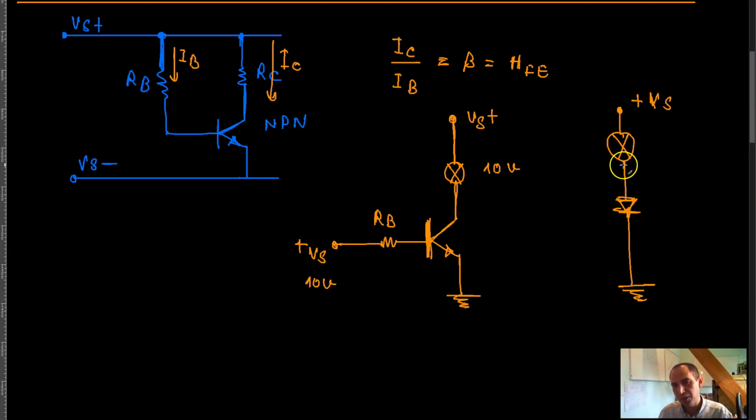Now, this is a series circuit, and in a series circuit you know that the supply voltage, depending on how much you have, some of this voltage is dropped on this load over here, some is dropped across this load over here, and the sum of these two voltage drops is going to add up to the whole supply voltage, right? So whatever portion of V of S is dropped across this PN junction, that portion is not given to the load anymore, right? And over here I want the whole voltage to be given to the load, right?